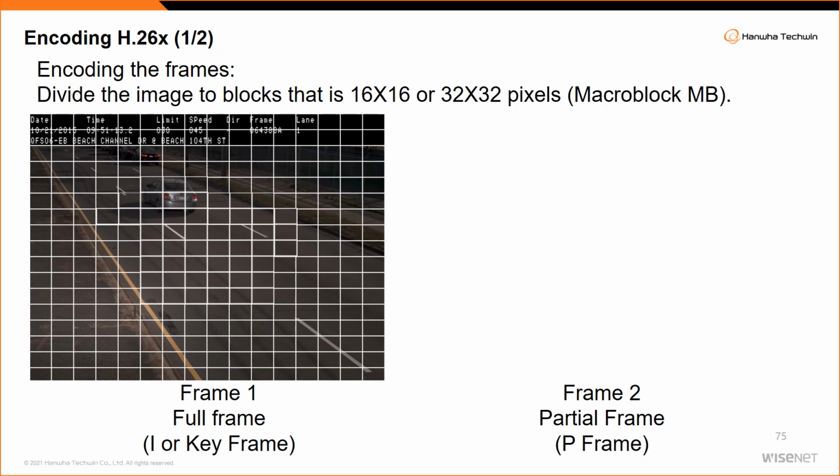Okay, and H.265 will be very effective for higher resolution. It can go all the way up to 50% reduction. But if you take half megapixel and you compare H.264, H.265, there is nothing to reduce. It's already a half megapixel. So there you cannot expect 50% reduction.